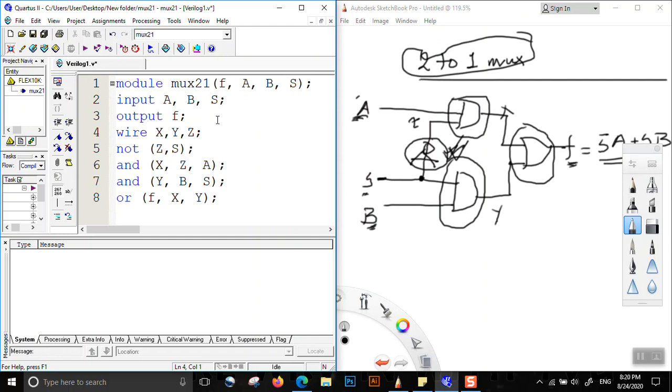This line is required if you want to make a circuit out of this code, but at present we do not plan on making a circuit out of this code. We just want it to simulate. If this line is included, the simulation will not run. So as a result, we comment this line out. This line should not be included in our code.